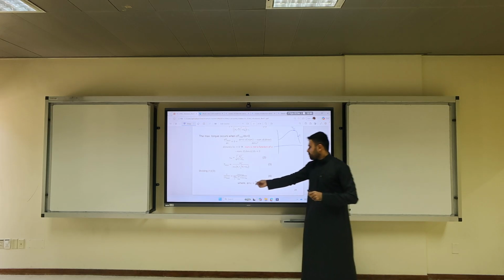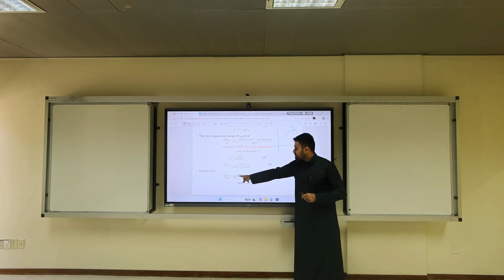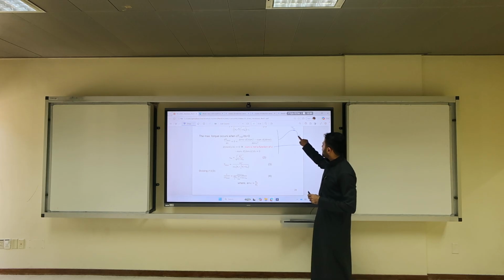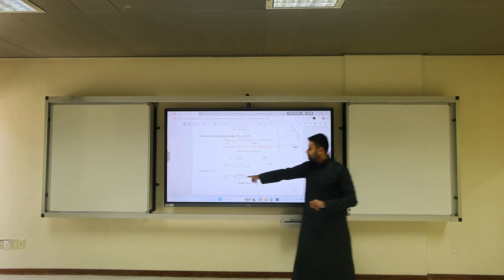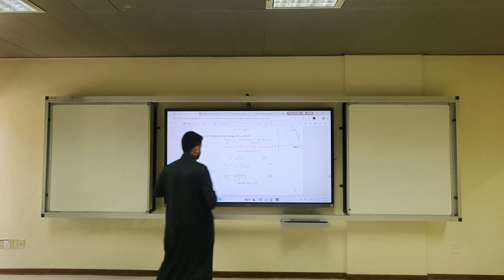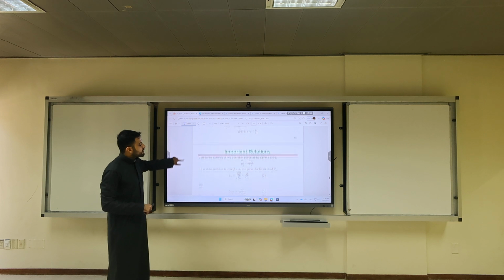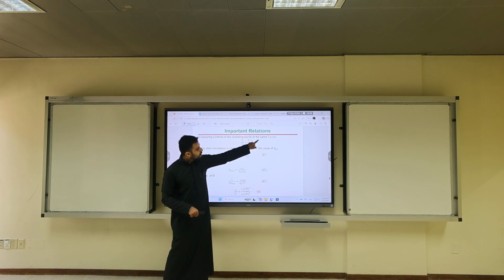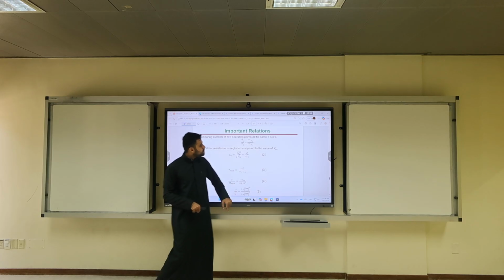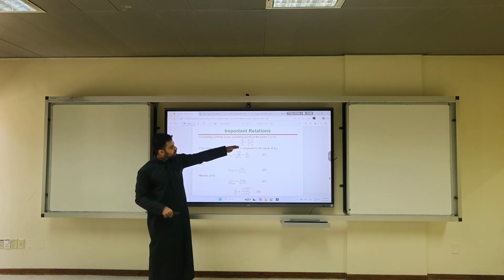Now, what he did here is he found this expression. You can have this, you can have that. Here you have slip. So if you change the slip, how much do you need to change it to get a ratio between T and half of T max? Remember, this 2 is to make the math easier. Now, it turned out that comparing currents of two operating points at the same torque and speed, you would have T1 over T2.